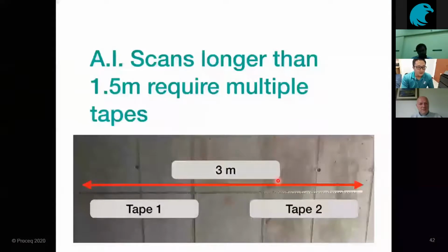We have this new function we call the artificial intelligent positioning system. I call this tape an AI tape. The Pundit 8000 transducer has an onboard camera which can automatically recognize this AI tape. You can test both horizontally and vertically. Each tape is about 1.5 meters, so we can continuously paste tape on the testing surface for up to 10 pieces. So we can look at this video.